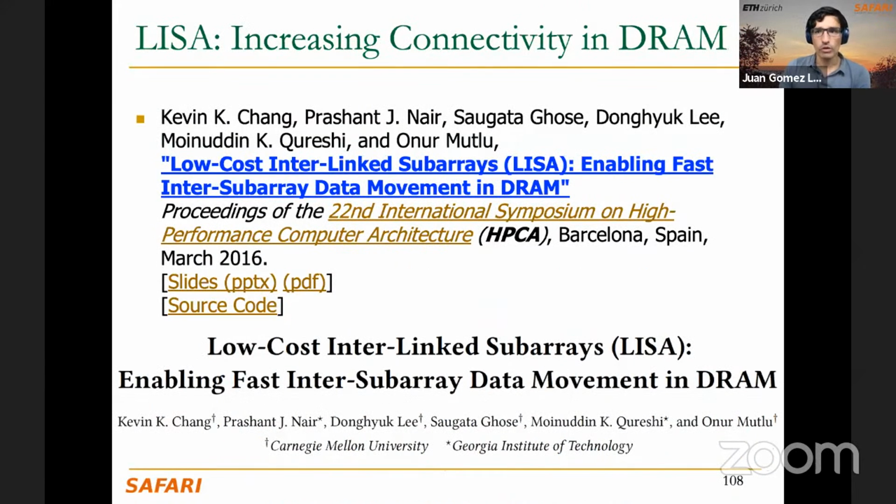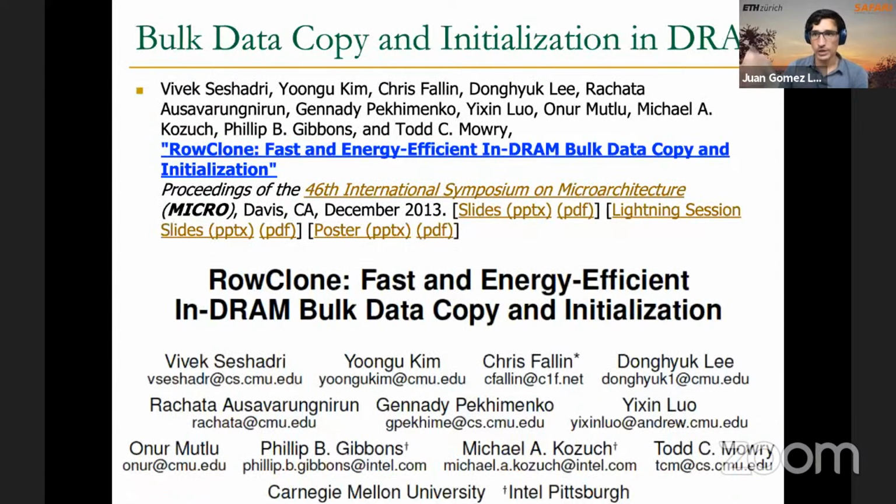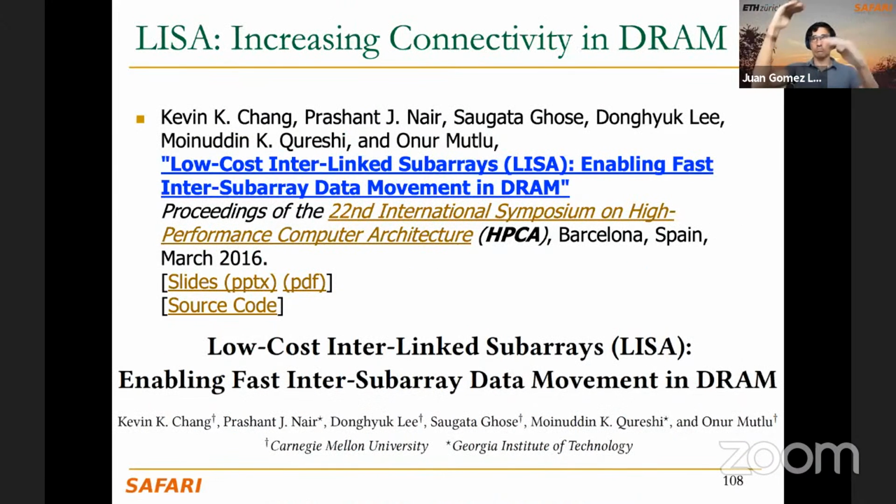Okay, so this is RowClone, and RowClone, by the way, connects to another big challenge of processing using memory, is the fact that, okay, you can maybe do copy inside the same subarray, you can maybe perform some bitwise operations with AND-bit inside the same subarray, but after doing some computation, for example, performing the element-wise addition of 2 arrays that are stored in different rows of the same subarray, we may need to use the output data in a different place, right?